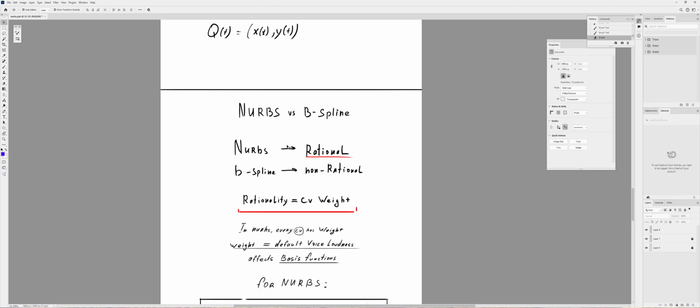So to understand what's going on, we now need to understand the second part of the naming. Non-uniform, we already figured out what that is. It's just the domain, the knot vector domain. Is it separated into spans, or is it one big chunk? So non-uniform we already understand. The next one is R. R stands for rational. So non-uniform rational B-splines is different from B-splines, but only in one nuance. The NURBS are rational and B-splines are non-rational. This is the only difference.